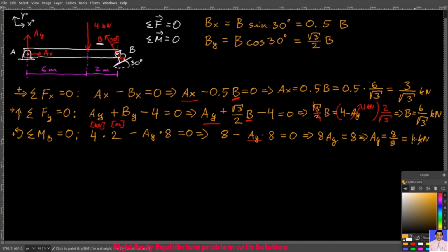What does it mean? Well, like we discussed in the previous part, in statics part 1, it means that all our assumptions about the directions of the unknown reaction forces were correct. A negative answer would have told us that the reaction force is in opposite direction to what we had initially assumed.